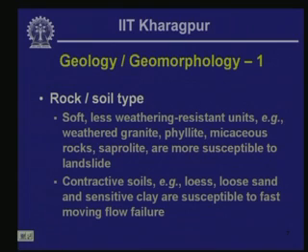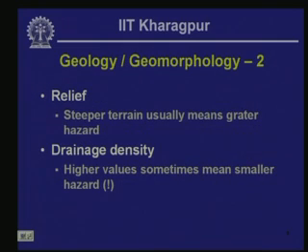If you encounter these soil units in a particular area, then those areas are likely to be more vulnerable in terms of landslide hazard. Relief of a particular area, how steep is the slope in a given area, is also going to affect landslide hazard. Steeper the slope, greater usually will be the landslide hazard.